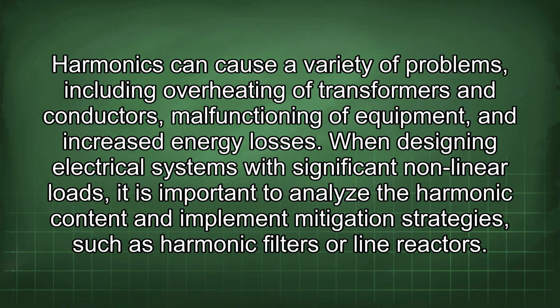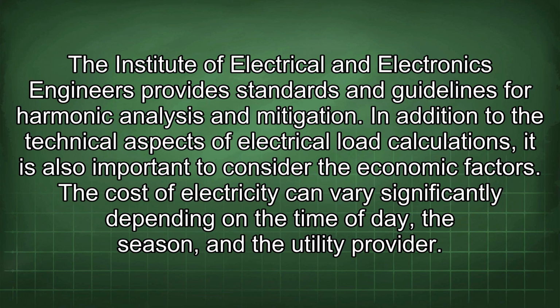When designing electrical systems with significant nonlinear loads, it is important to analyze the harmonic content and implement mitigation strategies, such as harmonic filters or line reactors. The Institute of Electrical and Electronics Engineers provides standards and guidelines for harmonic analysis and mitigation.